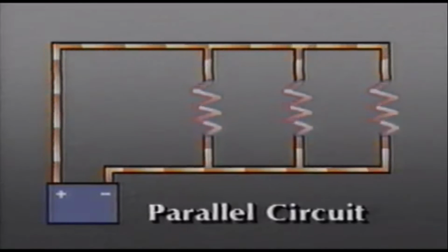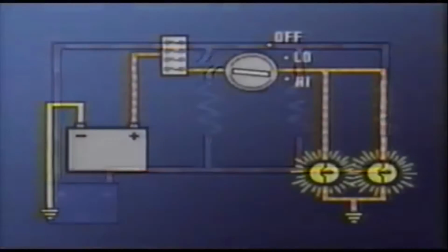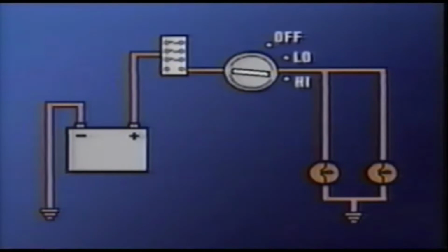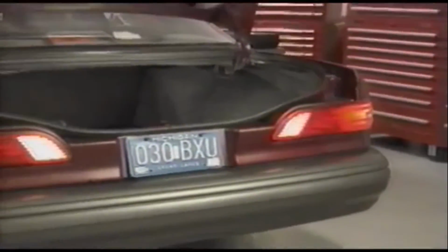In a parallel circuit, each load has a separate path to the source and to ground, and voltage across each load is the same. Since each load is powered independently, the failure of one load will not adversely affect the others. Certain conditions called opens will cause current to stop flowing, and other conditions called shorts will cause current to take different paths than ones they are intended to follow. Sometimes, a circuit may have backfeeds or spikes of reverse voltage pass through it that could damage an electronic component. Diodes protect these components by only allowing current to pass through the circuit in one direction.